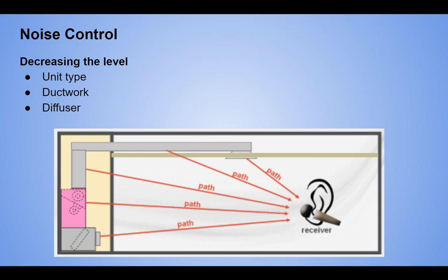If you let me know what your materials are, I can start to visualize from a sound standpoint, audiologically. Yeah, I butchered that word. I can start to see what that is. Likewise, when you cut your sections, I can start to see if you're going to have problems if you have a noise producing room right next to an acoustically sensitive room.